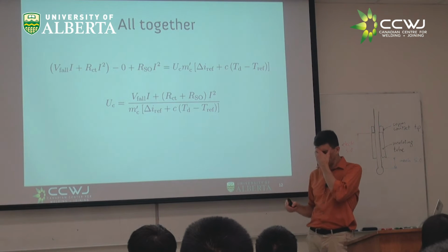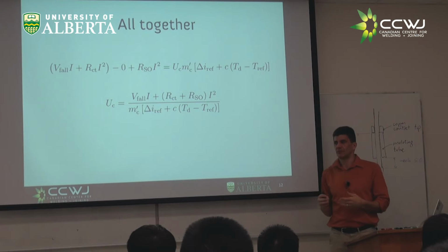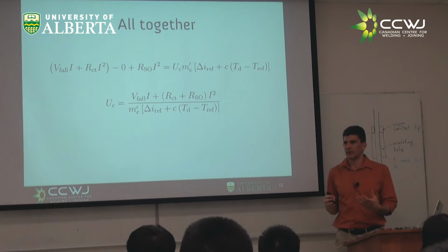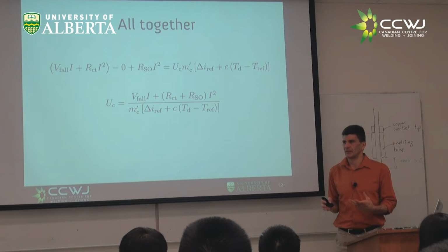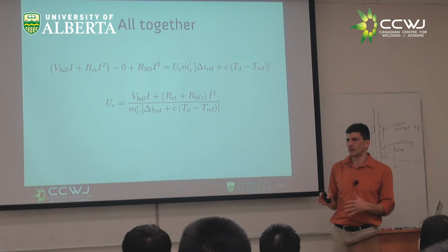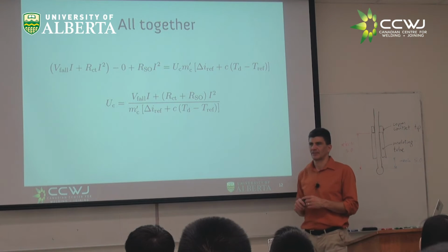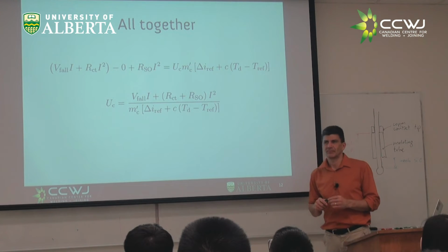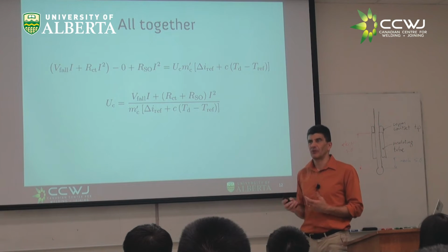Now, I don't have a slide for that, but I have uploaded the notes for, in the MIG guide for Lincoln, they have the same curves for aluminum. Question to you, do you think aluminum is going to give us like banana curves or more straight curves in wire feed speed versus current? It's more straight curves because the stick out doesn't matter very much in aluminum, right?